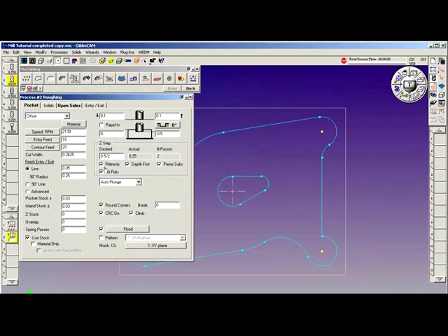Retracts. Retracts, when checked, will force the cutter to rapid up in Z after each level. If retracts is unchecked, the cutter will stay at depth and reposition at that depth and then feed down to the second or subsequent depth. Now, this could be a problem if there are features or islands in the way, it'll cut right through them. So to be safe, turn on retracts, view your toolpath, and then decide if you want to turn it off.